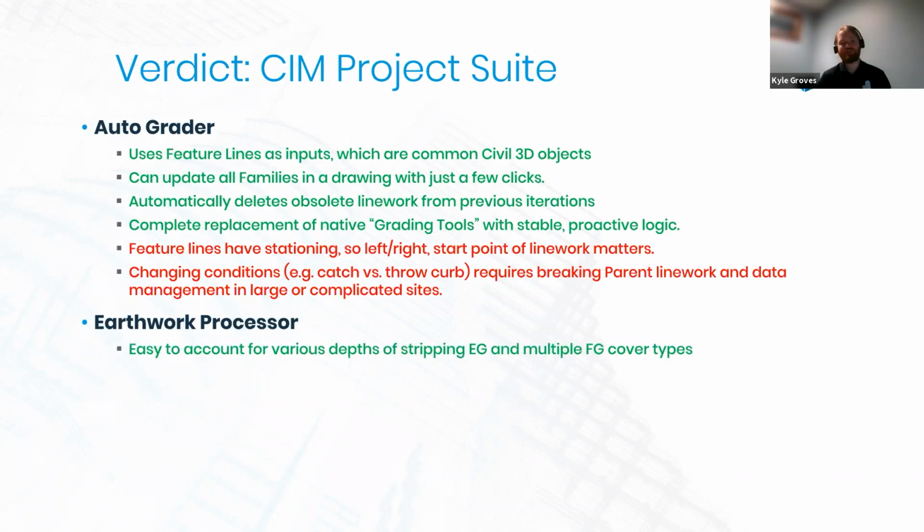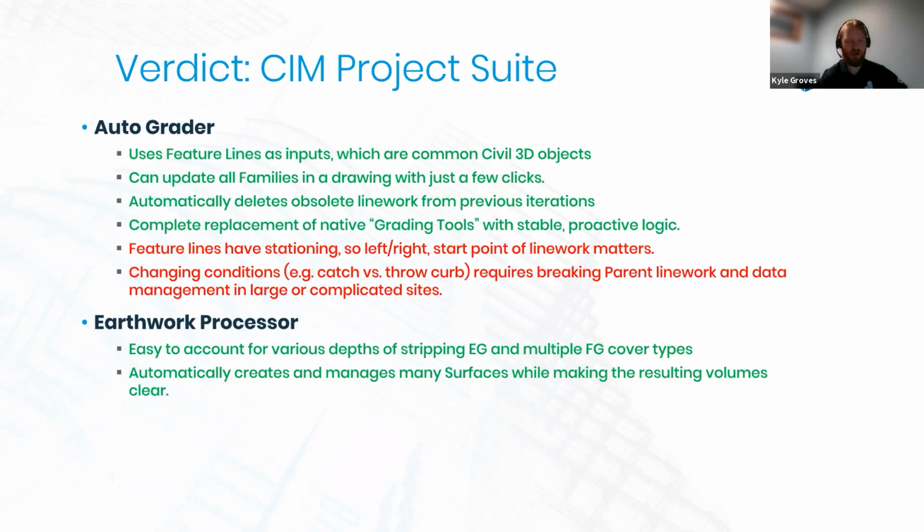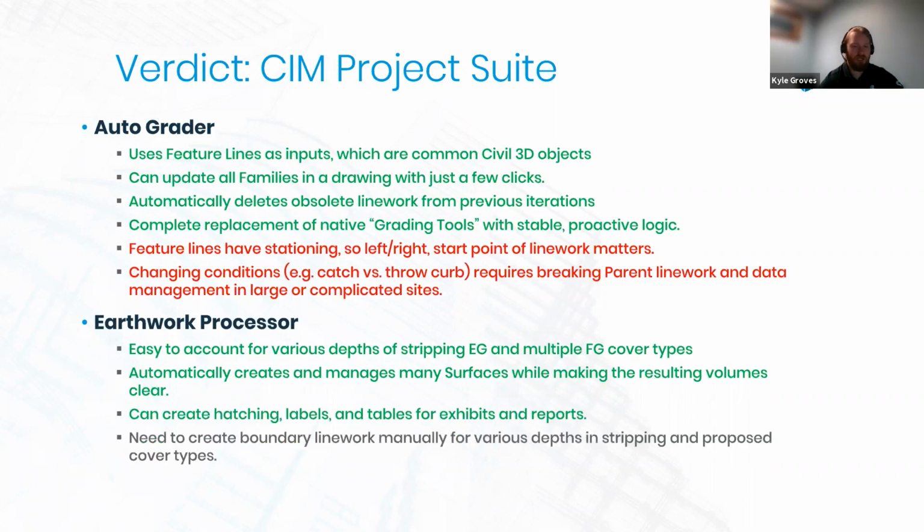For Earthwork Processor, this is going to make it really easy to account for our various depths, whether it's stripping existing or different cover types in our proposed conditions. It's also going to automatically create and manage many surfaces while making the resulting volumes very clear for us inside the tool and with output report. We can also have it create hatching for us, labels for exhibits, and then those tables can go in AutoCAD or out to Excel. However, again, you'll have to do this no matter what. You do need to create that boundary line work manually for those different areas. Your depths may change throughout your design, but if your horizontal information changes, you do need to update that for the inputs for this tool.